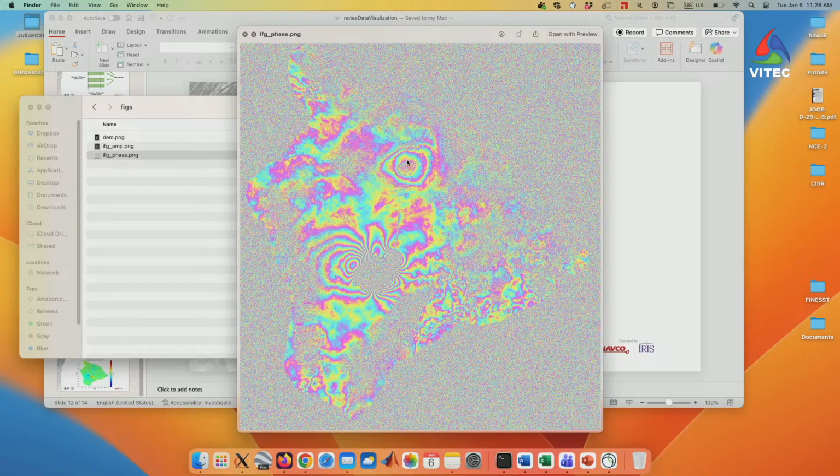And for this kind of signal, sometimes you can use a correction layer from a weather model based on that day's temperature, humidity, and the topography, and some in situ GPS zenith delay estimates, and sometimes they can be removed. Also on different days, this kind of signal looks a little different. So with many things, you could rule them out and average them out. And you also see some of these random fringes right here. So these are still tropospheric noise. These are more like turbulence noise that happens on a smaller scale.